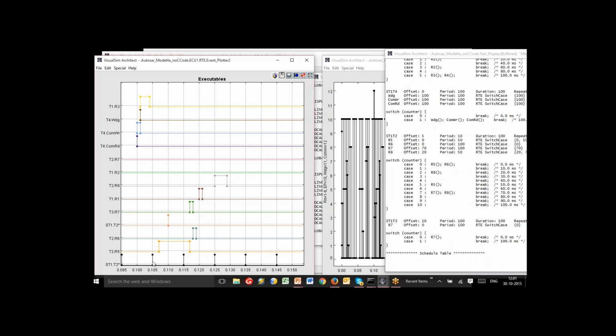What we're going to notice is that this is the T2, or the trigger for task 2. But notice that the actual task does not get executed until this point over here. The reason is this task here, which is the prior task, only got triggered at this point, and it ended up right over here, which means the next task couldn't start up until this point over here.